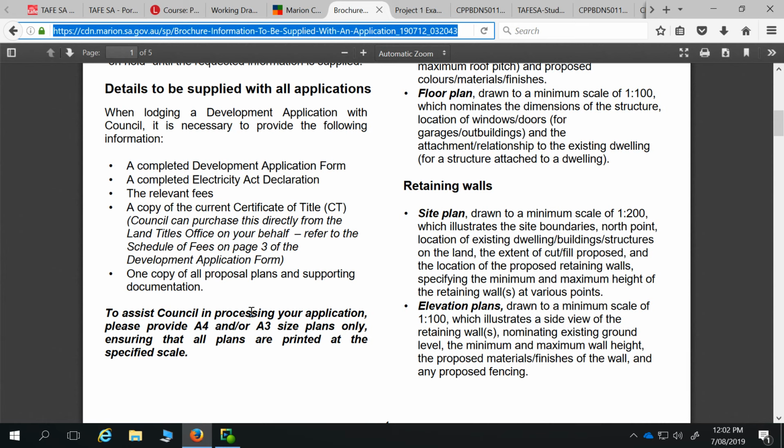So I've been talking to council recently for a house that I'm working on. And in the development plan, it says that you're allowed to build on the boundary on one side up to a certain distance back, I think up to 8 metres. But the other side has to have at least 1 metre setback. My proposal, however, is in a heritage conservation area, and it doesn't have any setback requirements other than the average of what the neighbours are. So there's nothing mentioned about the sides.